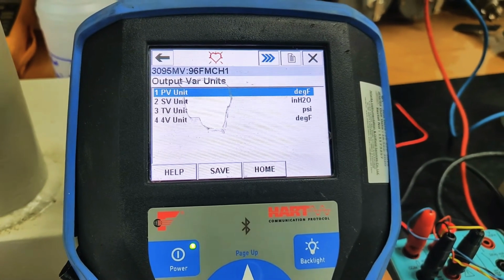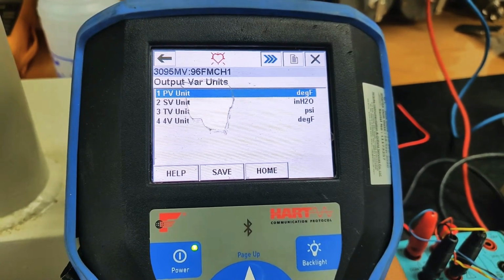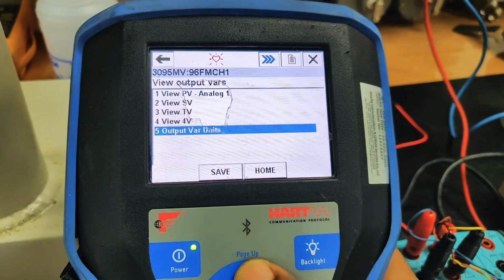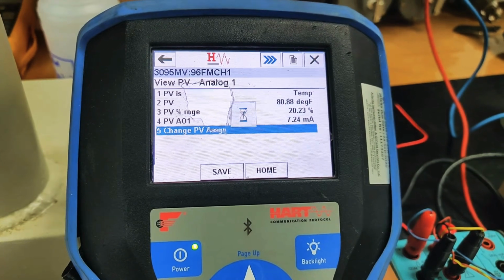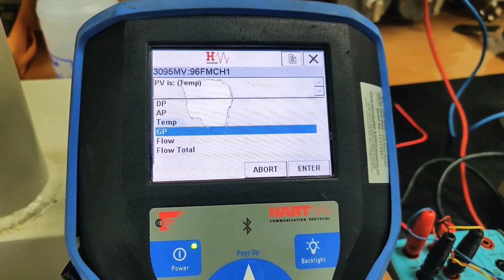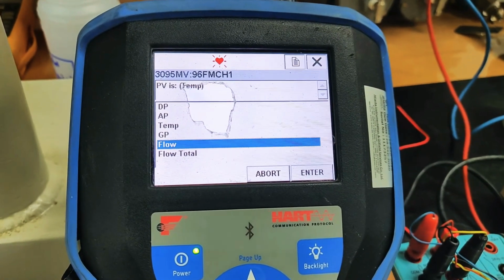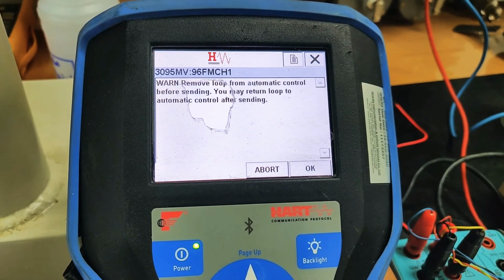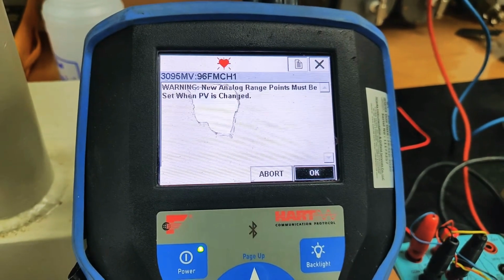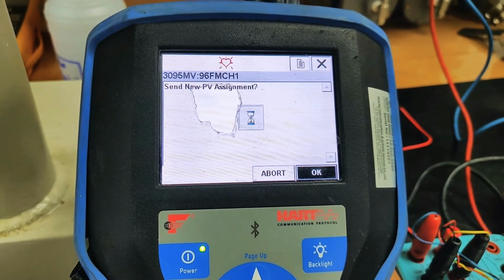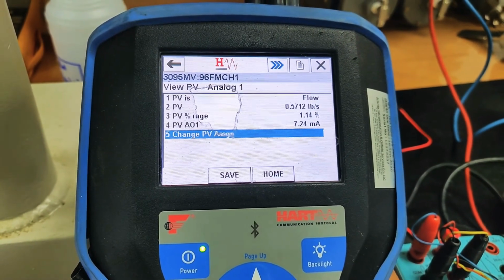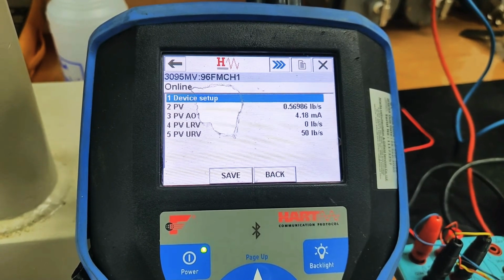You can easily connect to maximum and zero, and take the corresponding milliampere correction. If you have any error, with the same PV selection you can calibrate using zero calibration, or higher and lower calibration. Like this, you have to do all the variables individually.